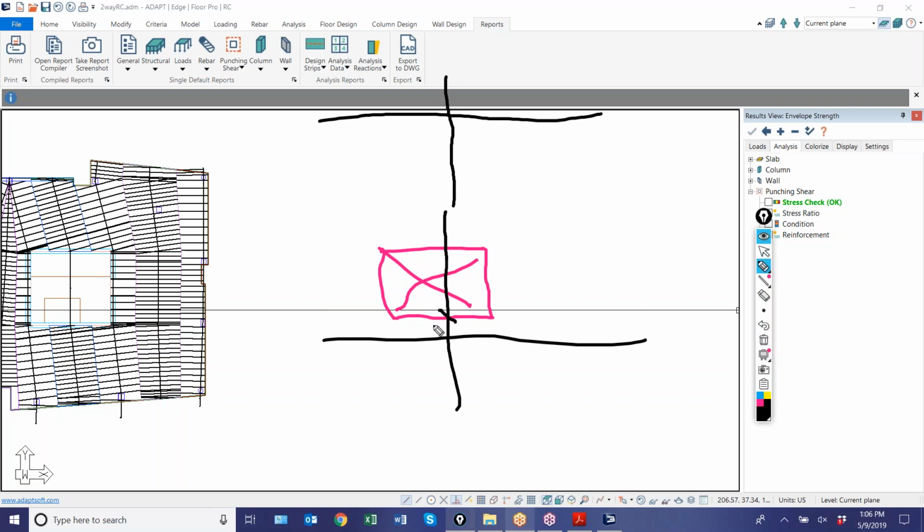This comes into the opening and exits out of the opening. So now in reality, when we look at this physically, we have slab, an opening, and then slab. This is like the section of the slab here and here. When the program designs for this, it combines it. It says add this to this and you get some conglomeration of these two sections. But in reality, there's a bit of discontinuity there.